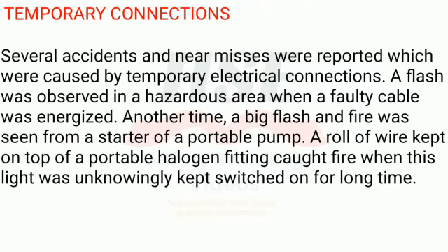Temporary connections. Several accidents and near misses were reported which were caused by temporary electrical connections. A flash was observed in a hazardous area when a faulty cable was energized. Another time, a big flash and fire was seen from a starter of a portable pump. A roll of wire kept on top of a portable halogen fitting caught fire when this light was unknowingly kept switched on for a long time.